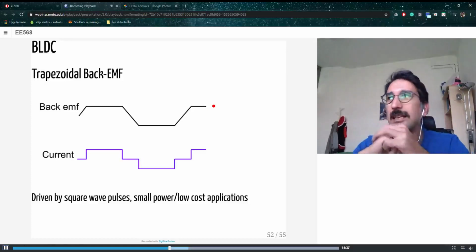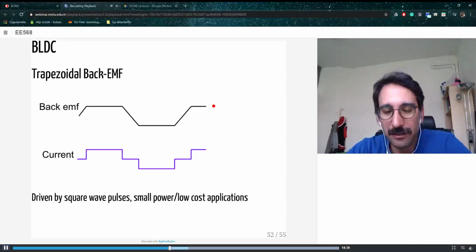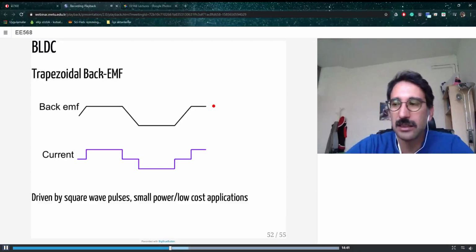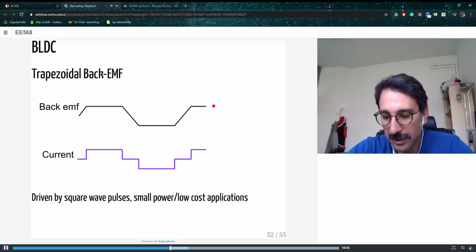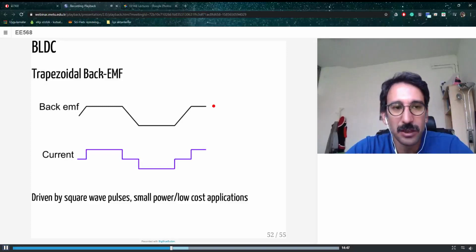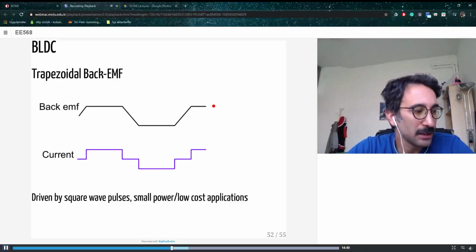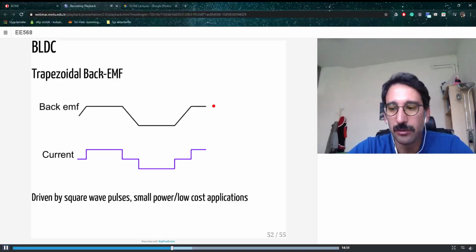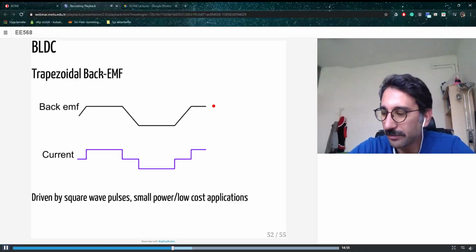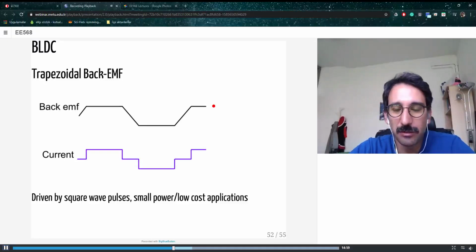Again, it doesn't mean every small motor is BLDC and every large motor is PMSM. Usually it is specified in the datasheet, but if you have any doubts, just connect the oscilloscope and rotate the motor at no load with your hands, to see the waveform of the induced EMF voltage.